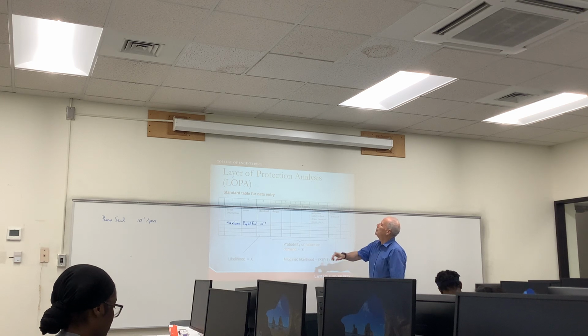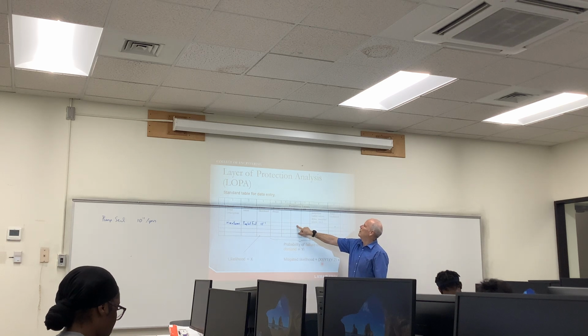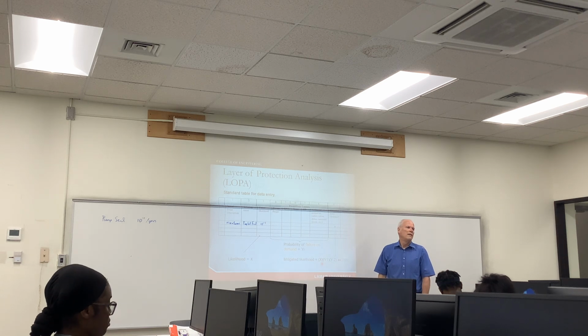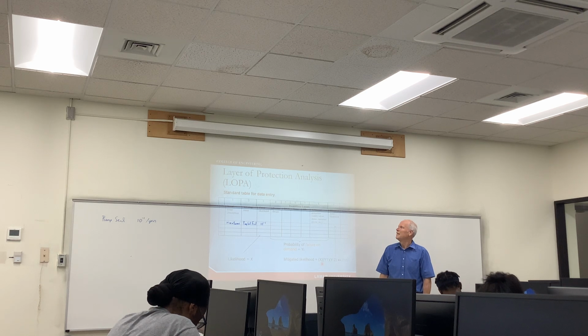This is not process design, it's not basic process control system, it's not alarm. How do you know that that pump still failed? Oh, pressure. The pressure change. And then also you'll see it'll be leaking, and your flow. How does the operator know it? I mean, how do they know to go out there and look at it? Just gotta know.